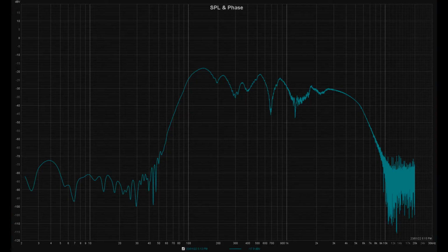And after I ran the first scan, surprise, I got this not very nice output. This is how the equalizer performs after power up. This graph, obtained using the testing environment that I described, helped me confirm a suspicion that I had: when the device is powered on, it doesn't get initialized properly.